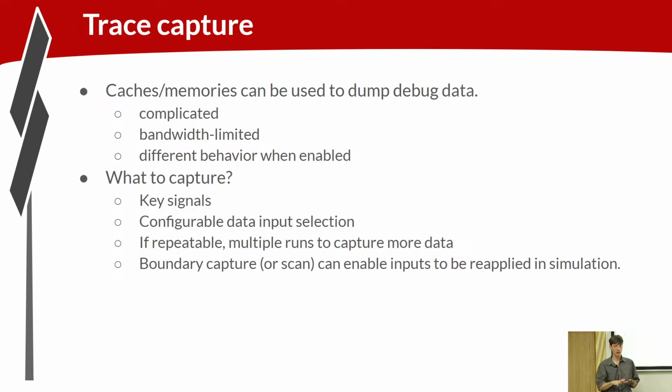So, generally the nature of these designed for debugs is you've got a whole bunch of state in the design that you want to be able to capture. You've got this network that's funneling all that data and a bunch of configuration that's allowing you to select amongst all this different data to funnel it down to some set of data that you can actually capture cycle by cycle.